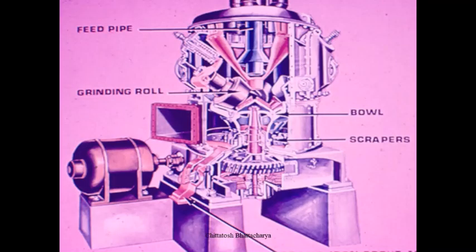We have a seal air supply system through a seal air fan, which supplies sealing air to the roll journal assembly upper skirt joint of the lubricating oil supply system, to continuously seal the lubricating oil supply from the external coal dust and primary air dust-laden arrangement. Besides that, at the vertical shaft, just below the scraper assembly, we have a seal air supply ring, and this bracket supplies the sealing air at the scraper housing joint, so that coal dust cannot ingress inside the gearbox.